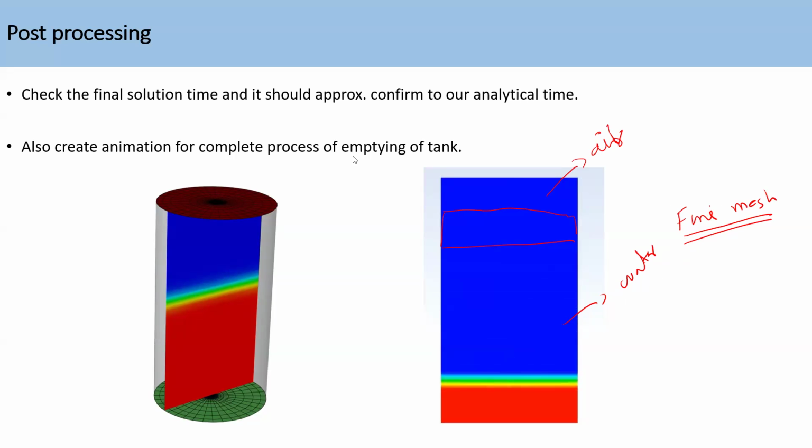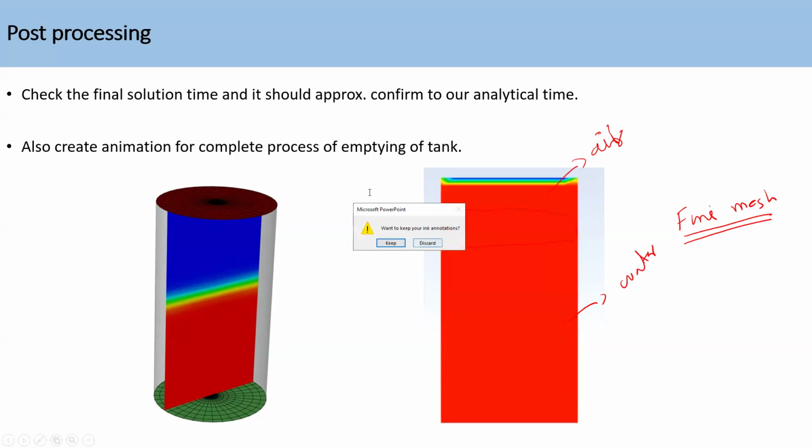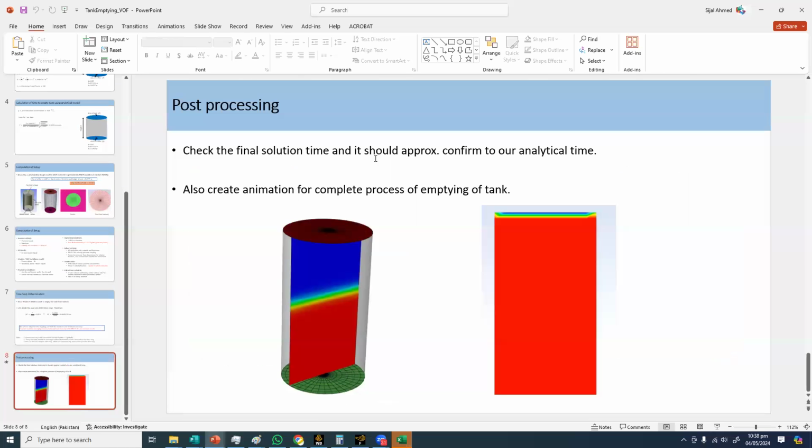May I ask another question? Maybe it's not related, but I have a student license. I don't know if it will be capable of solving the problems in this workshop or not. The student version has all the capabilities. The only issue is that the student version can only solve up to 512,000 cells, not nodes, but cells. That is a limitation of the student version. That's the only problem.